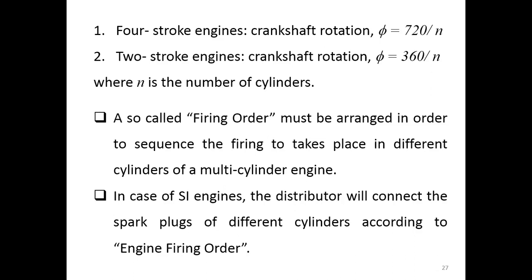Okay, so because of this, we need to have a firing order. This firing order must be arranged in order to sequence the firing that will take place in different cylinders of a multi-cylinder engine. For an SI engine, we have the spark plug, so the distributor will connect to the spark plug at different cylinders according to the engine firing order.